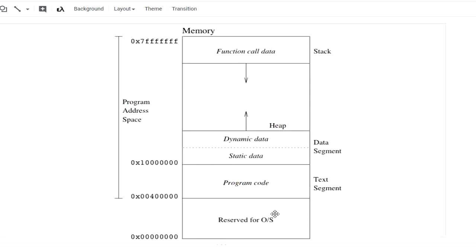Here in this diagram, we saw that the program code starts at 400 hexadecimal, and then it progresses up. It was 404 for the next line of code. The addresses of the lines of code are in this location: 404, 408, 412, etc. And who is pointing to that? The PC, the program counter. He is in charge of keeping track of where I am.